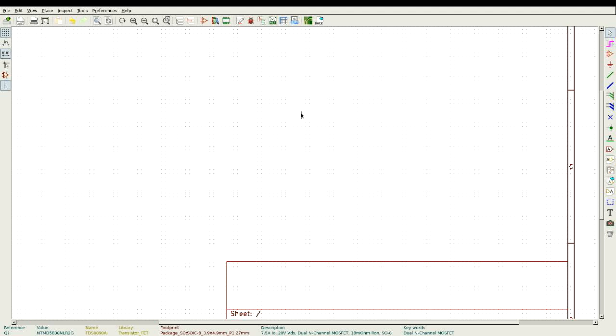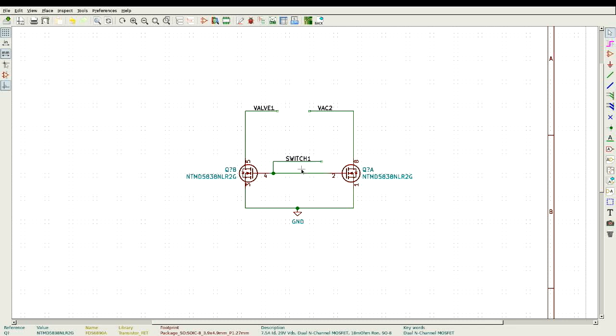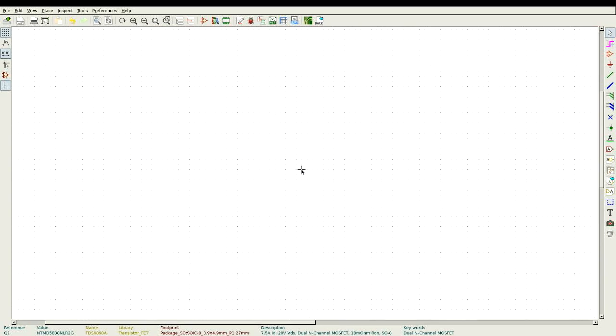So the first thing is I'm using keyboard shortcuts. I've given you a list of the keyboard shortcuts on the piece of paper down the bottom corner. I strongly suggest that you start by using the keyboard shortcuts. The CAD program is really designed to be used with one hand on the keyboard in that fashion. So the first one that's important is zooming in and out is done with F1 and F2. This is a little bit exciting. The best way to navigate the document is by zooming in and out. It will zoom in where your mouse is. So if I were to move the mouse up, I zoom in, it recenters. If I wanted to go to a different portion of the document, I zoom out, I recenter my mouse, and I zoom in again. CAD programs all have their own special way of working. There's no point fighting it, you will lose.